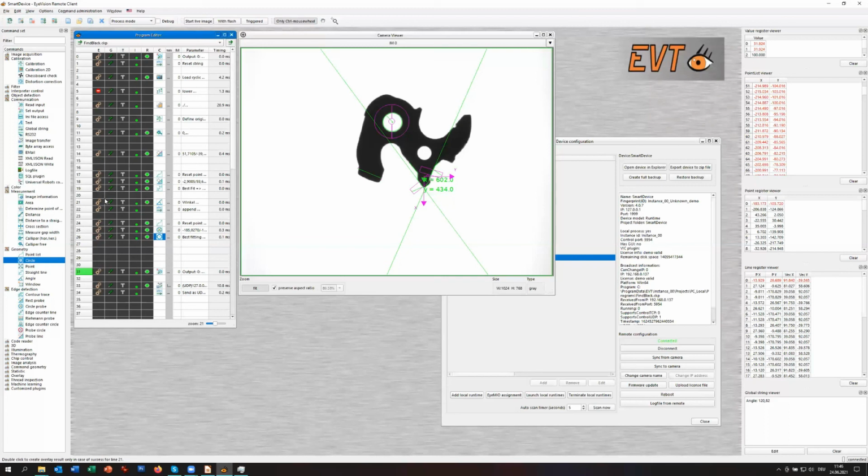You see, we have the hand-eye calibration, which allows you to do the calibration of the field of view with the camera calibration. Based on this camera calibration, you have at the end the registration between the robot and the camera, and of course this works as well on a normal PC.